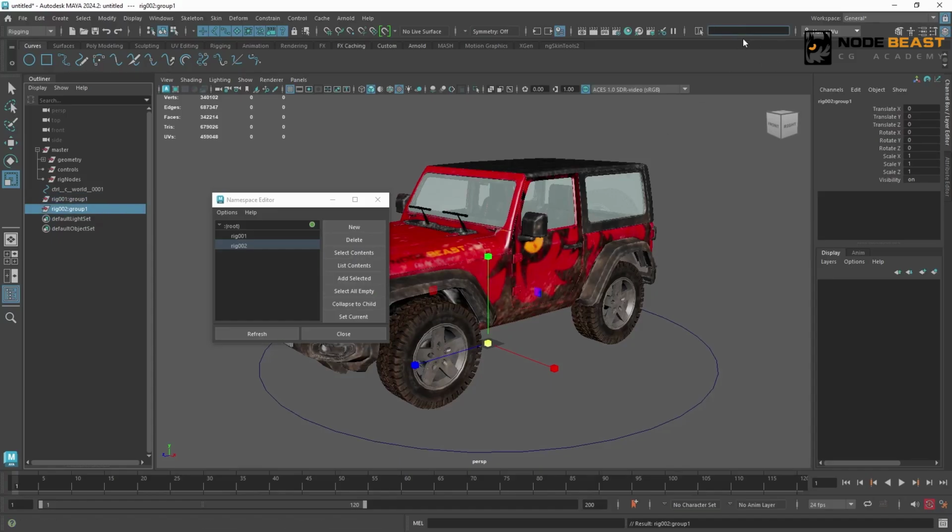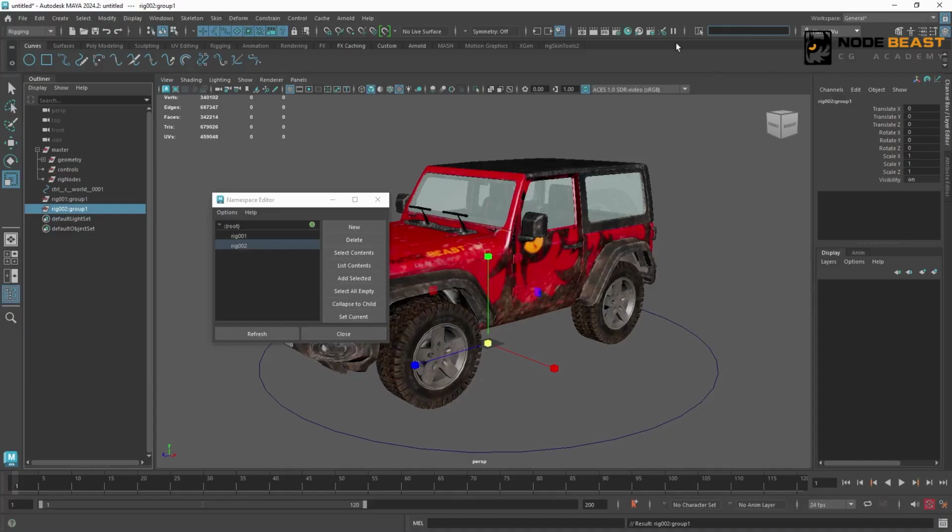And it's also very easy when we want to search for them. For example, I want all the Group 1 nodes here. Although I don't know what the namespace is, I know there definitely is a namespace. So I use an asterisk here, followed by a colon. We know the colon is the symbol that connects the namespace and the actual node. And then we know the part after is Group 1. So here I type Group 1, press Enter. This will select both of these nodes.